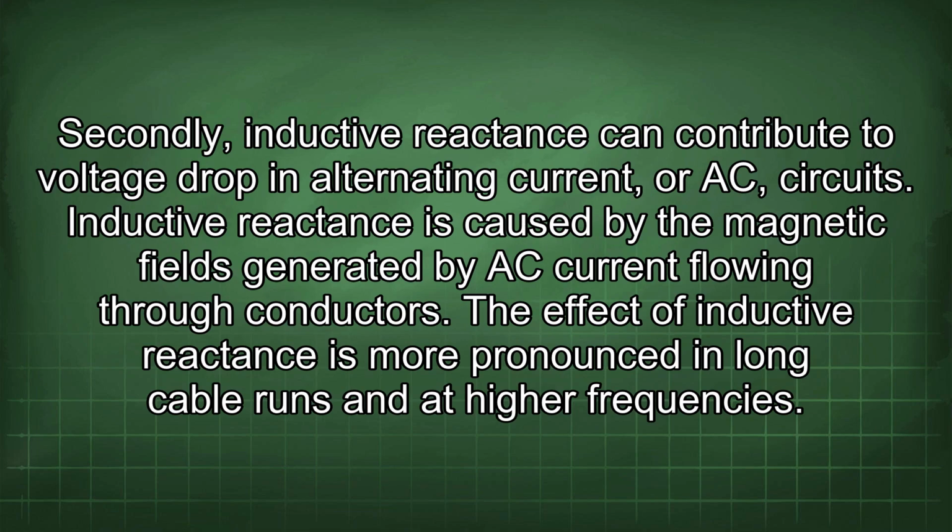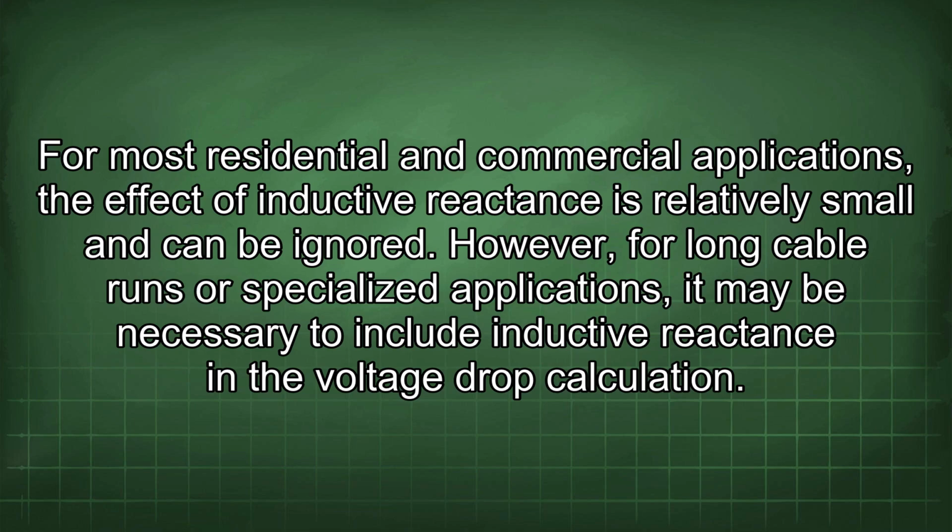Secondly, inductive reactance can contribute to voltage drop in alternating current, or AC, circuits. Inductive reactance is caused by the magnetic fields generated by AC current flowing through conductors. The effect of inductive reactance is more pronounced in long cable runs and at higher frequencies. For most residential and commercial applications, the effect of inductive reactance is relatively small and can be ignored.